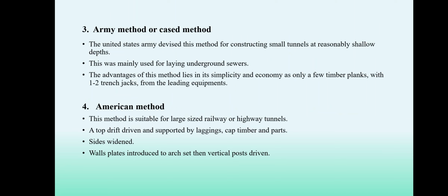Army method or case method. The United States Army devised this method for constructing a small tunnel at reasonably shallow depth. This was mainly used for laying underground sewers. The advantage of this method lies in its simplicity and economy, as only a few timber planks with 1 to 2 trench jacks form the leading equipment.